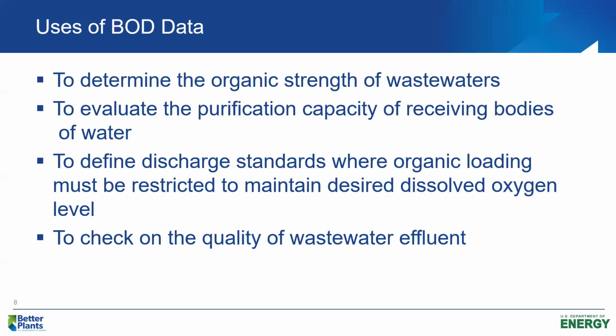And in most states, the minimum DO that we like to maintain is 5 milligrams per liter. If we're out west somewhere and we've got a trout stream, we may want to maintain a minimum DO of 7 milligrams per liter.